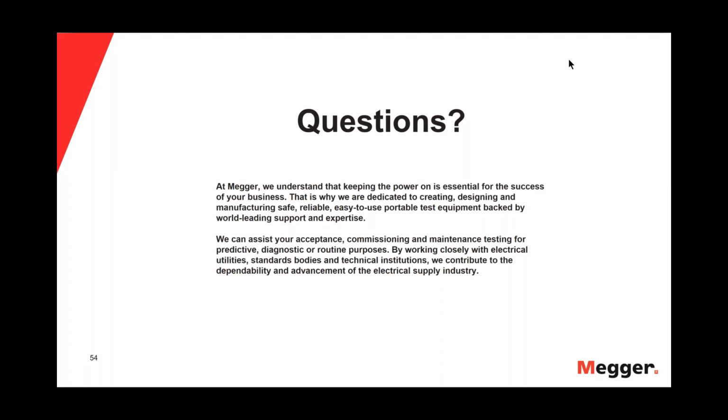The nice thing about impedance changes is it's a lower impedance or a higher impedance, either way is an indication, but it also shows you exactly where that is. That is a big advantage. When you measure leakage current, you only know, okay, I can have leakage current along that cable. I have no clue where that is. With the impedance change, I can figure out where that location is.